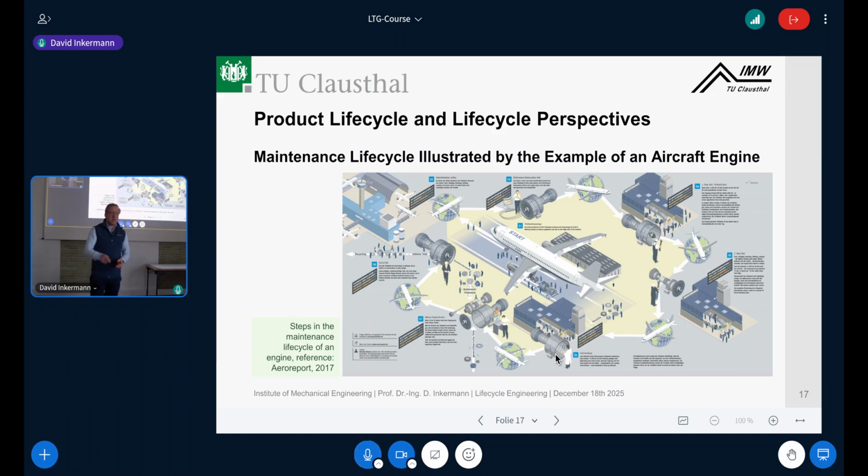They are running this kind of maintenance life cycles. For each airplane, in that case we have 2 engines, and normally you have between 6 and 8 engines in addition, because while maintaining one engine, the airplane should be operated continuously, and that is where it uses other engines.